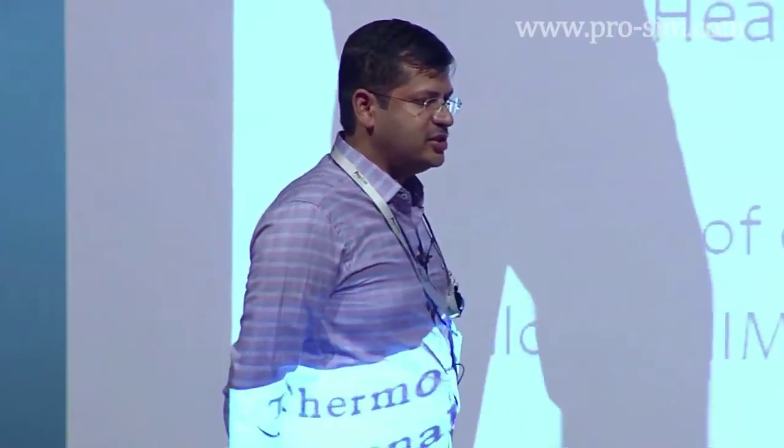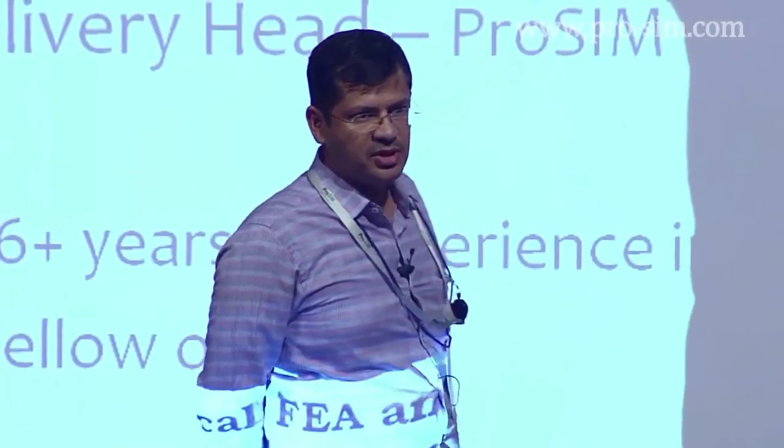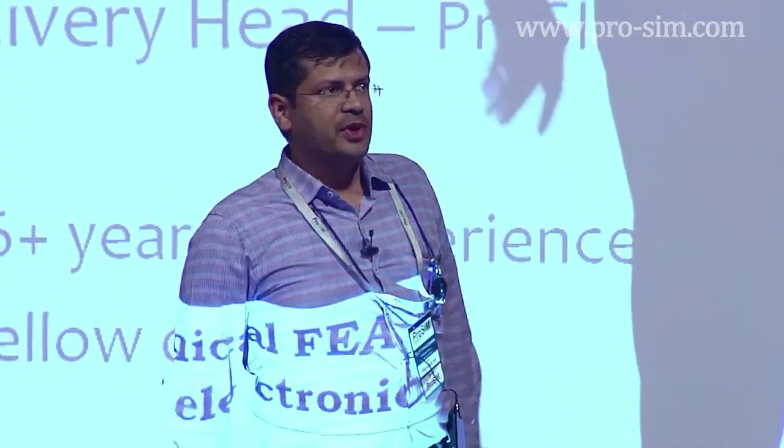Material, there were different material structures like PCB structures. We did not get enough details from literature. The damping value which you used is a bit less. 2% structural damping. Yes. I think that's less. It's small. No, predominantly yes. In steel structures, we use 2%, 3% structural damping. Some kind of plastic, right? No, the chassis materials have an aluminum base, and we had relatively very few PCB structures of non-aluminum. So overall, the structure was predominantly aluminum.